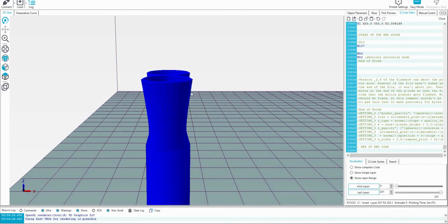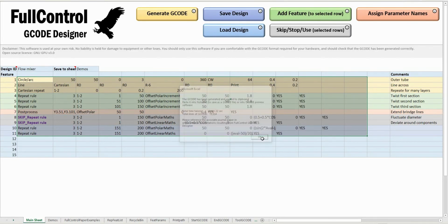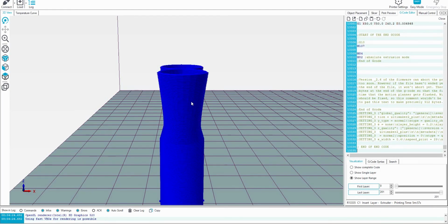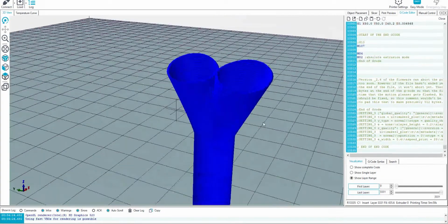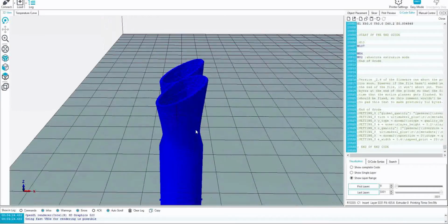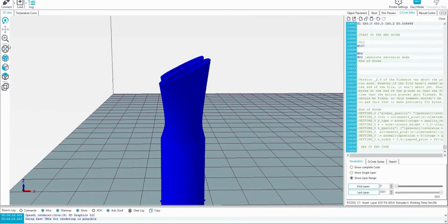So any segments of the print path to the right of the center point are going to move slightly higher, and any to the left are going to move slightly lower. This is in the Z direction, and it's only going to apply for this top section where we're having the split. And what that's going to result with is this structure. So we've now got our angle, and we've done this with non-planar layers.